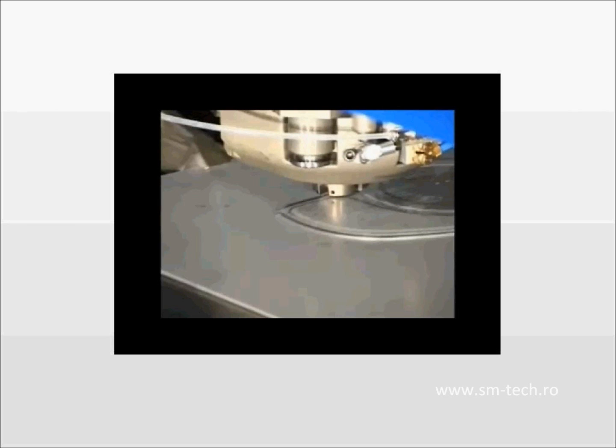Some machines will allow you to ramp the tool down so you can bring that wheel slightly over the top of the sheet and then ramp the wheel down slightly as it starts cutting. That can really ease that distortion that you see at the beginning there. It's a little more complicated from a programming standpoint, but it definitely can help.